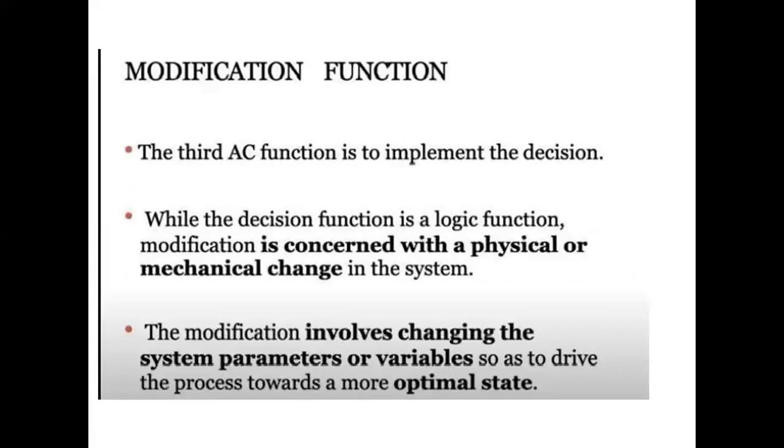When it comes to machining, we are trying to firstly identify the performance, like what may be the cutting conditions. You will see what the temperature is, what quality is being produced right now. You'll see all these things. Second thing, you will make a decision what is to be changed. If the temperature is too high, maybe I should decrease the feed rate. That is the decision that you are trying to implement. So decisions will be finalized, what is to be done.